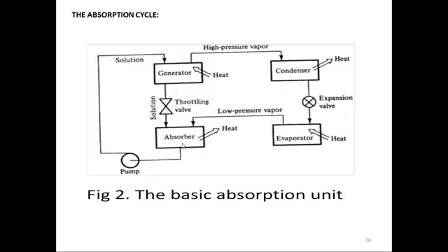Similarly, the absorber is rejecting heat because the absorption of the water into the lithium bromide is an exothermic reaction, so it will give up some of the heat. So low temperature heat is being rejected into the environment here, and the condenser will reject the high temperature heat from here. So if you compare it with the vapor compression refrigeration cycle, you can say that you have two processes